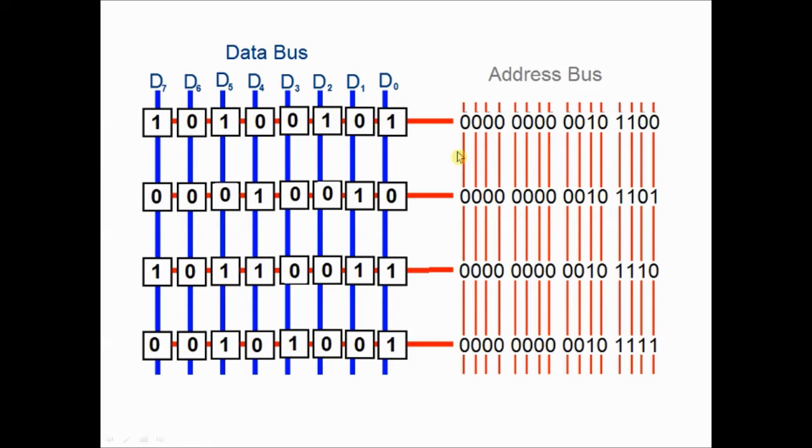Now if we were to zoom in on some of the RAM, it would look something like this. You notice that there are 8 bits going horizontally, and it's connected up to 1 each to a data line, D0 through D7. You note the octal comparison there. That's why it was important for us back in the day to learn octal, so you could program these numbers directly without having to use binary. But D0 hits bit 0 of every single one of the 64K memory locations, just as D4 hits bit 4 of every one of the 64K.